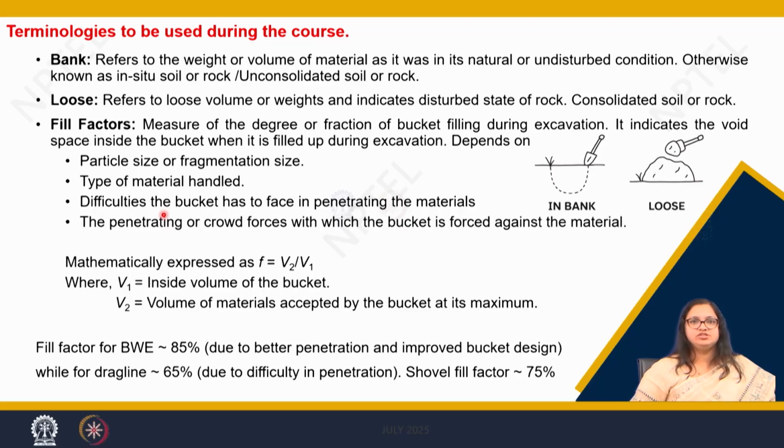Let's say there is a virgin face of the rock onto which the bucket of the excavator has to penetrate. If it is a soft ore body, then the penetration would be easier and the fill factor will be more. However, if the ore body is hard, there will be difficulty in penetration and the fill factor will be less.